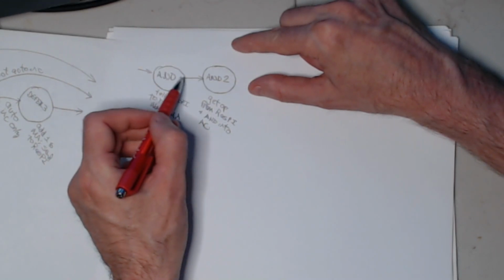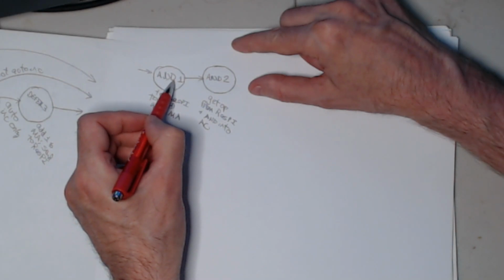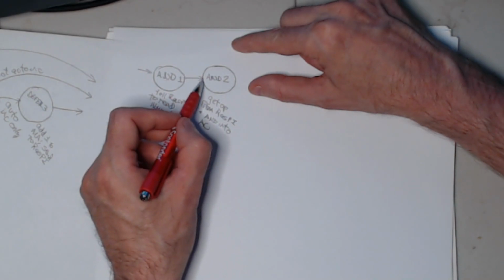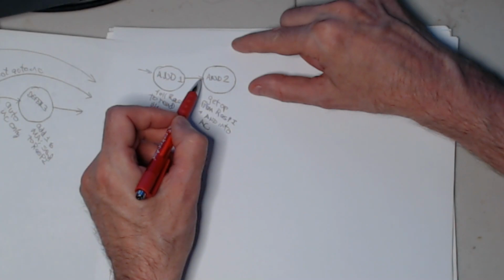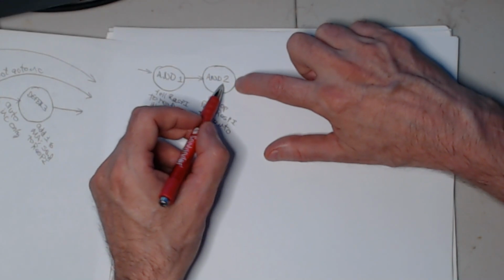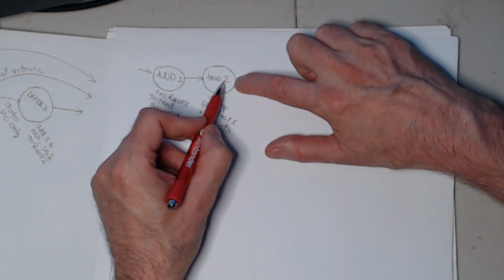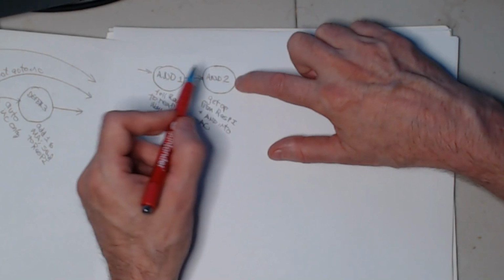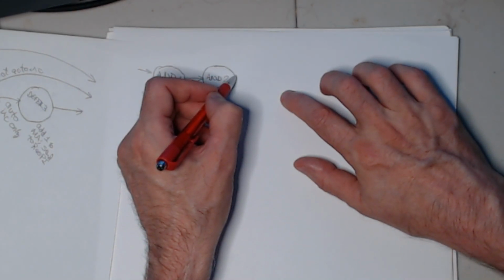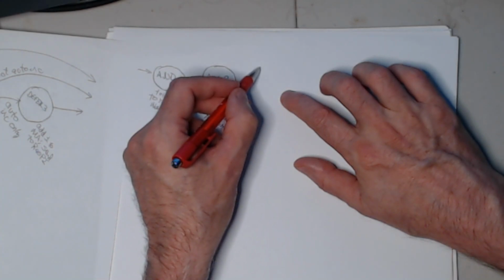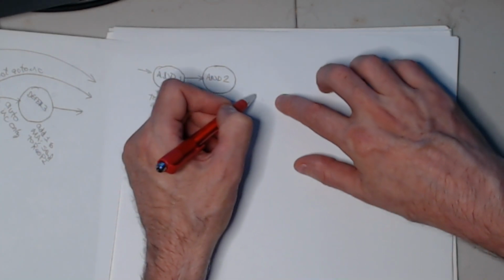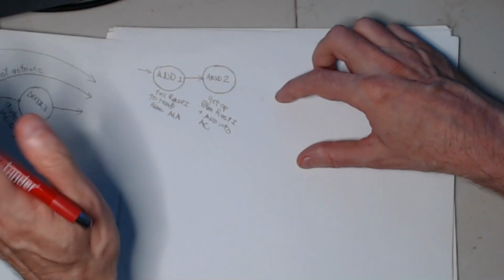So, and this is an always, okay? So when it gets into AND 1, it's always going to do AND 2. So this arrow is just unconditional. It always goes to AND 2, okay? And this is the last cycle of an instruction, and we'll talk about what it does next later on, how it figures that out. Basically, it goes one of two places. It either goes to fetch 1 if there's no interrupt request, or it goes to that interrupt acknowledge cycle if there is an interrupt request. But we'll talk about that later.